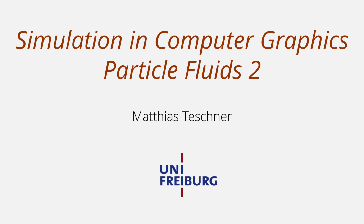The accelerations at a fluid particle are described by the Navier-Stokes equation. So the Navier-Stokes equation is a differential equation that governs the velocity of a fluid particle. I've discussed that the accelerations in the Navier-Stokes equation account for various physical aspects, such as viscosity and incompressibility, and we have seen that these accelerations require spatial derivatives of certain particle quantities, for instance the Laplacian of the velocity or the gradient of the pressure.